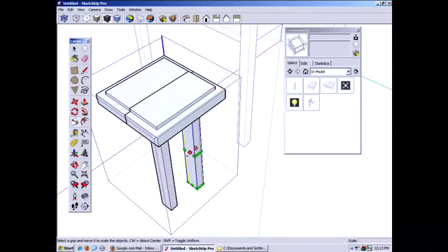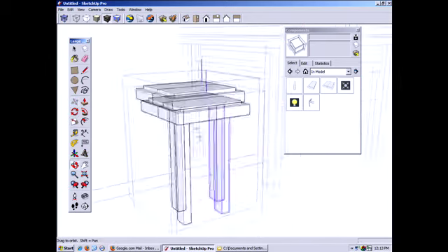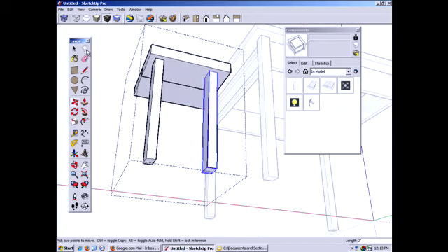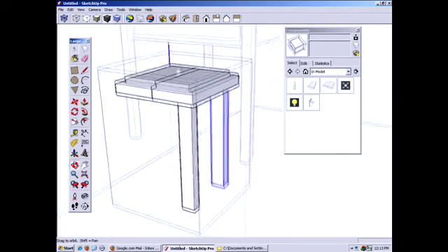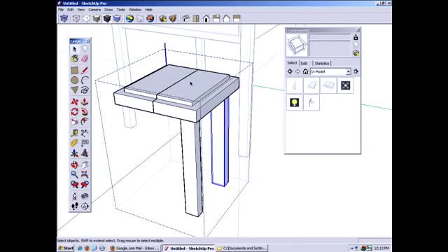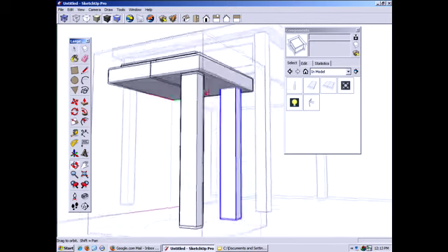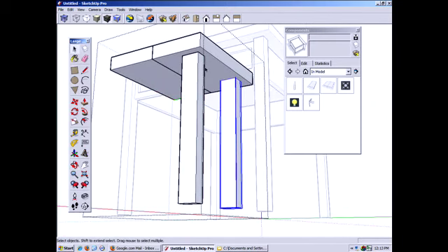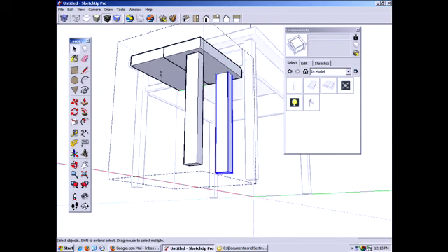And I'm going to copy this across, scale it, and move it over. Now, someone brought up earlier this idea called paste in place. By drawing this outside of the seat, if you will, we've been able to create it as a component and not have it tie in with this other. However, we do want this replicated on the other side, of course. Well, we can do that very easily with something called paste in place.